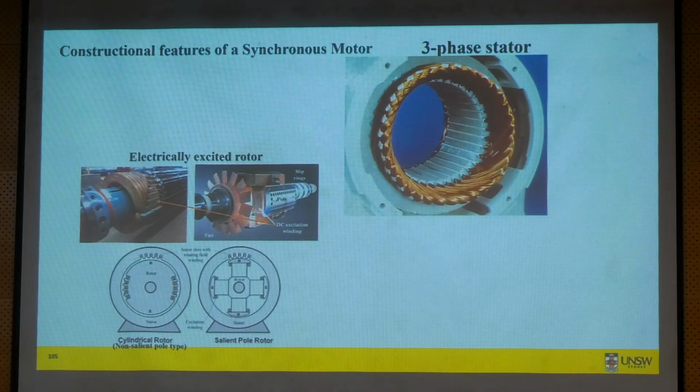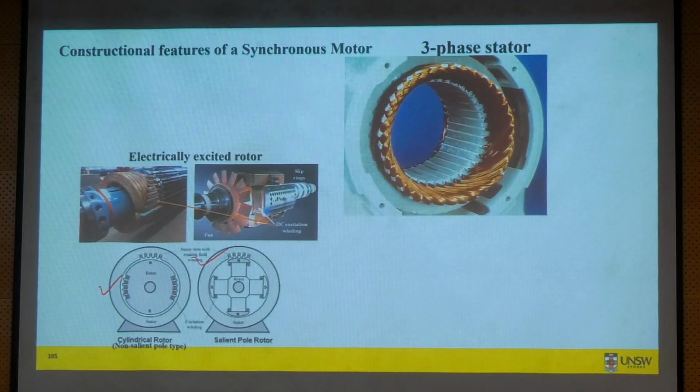This is a conventional synchronous machine here you are seeing. You will have a three-phase stator. Your rotor could be either salient pole or cylindrical pole rotor, right? Now the stator for a synchronous machine, a PM synchronous machine could be same, three-phase distributed winding stator.